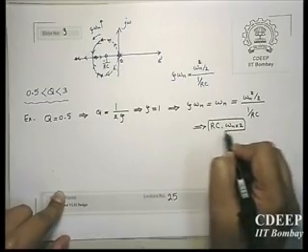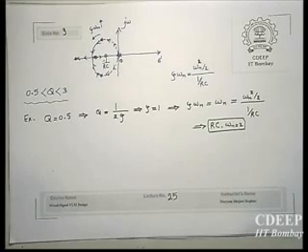So if you choose zeta equal to 1, which is Q equal to 0.5, this means that your resonance frequency of the loop will be 2 times omega 0 of the filter.